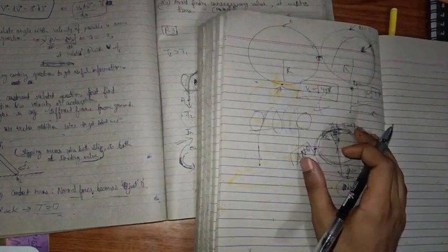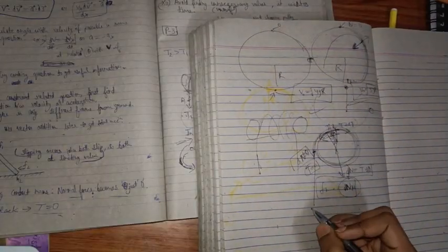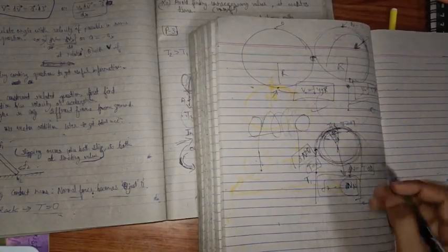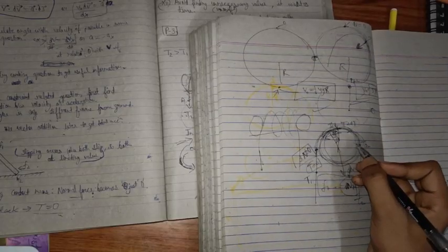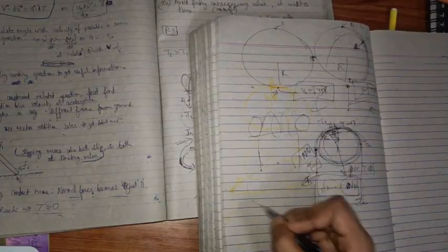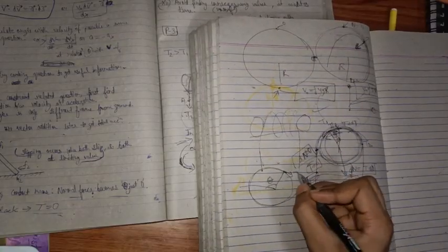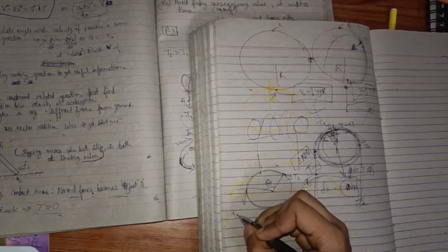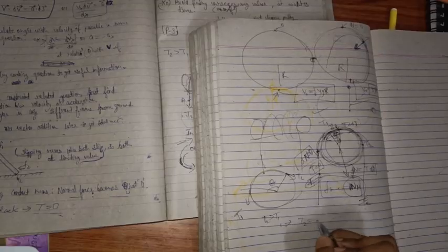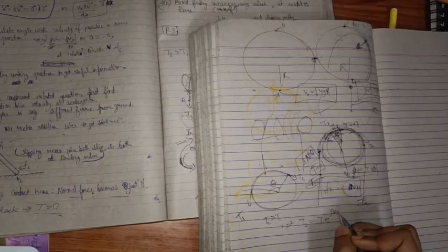And let's say in a given case, the tension does not become zero in this path, and in that case, let's say the other end has some T1 tension and this end has T2 tension. If this cylinder is wound with a rope and I am rotating about theta angle, and this is, let's say, T2 tension at this side and this is T1 tension at this side, let's say T2 is greater than T1, then in that case we get T2 is equal to T1 into e to the power integration of mu d theta.